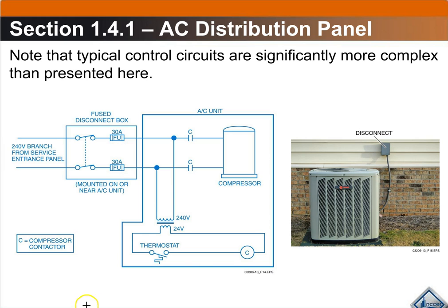You don't have to do a tag out lockout, because if you turn the circuit breaker off inside the house and then you're working on it and the homeowner comes out and turns it on, you get zapped. So this disconnect protects you here so that doesn't happen.